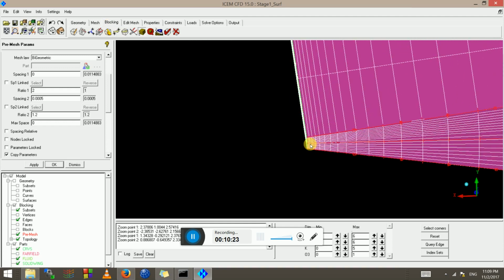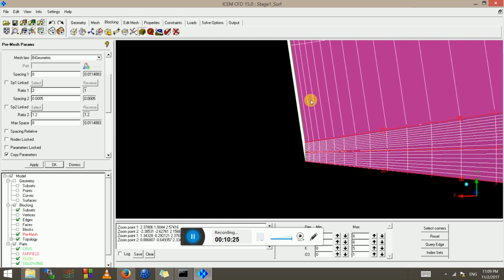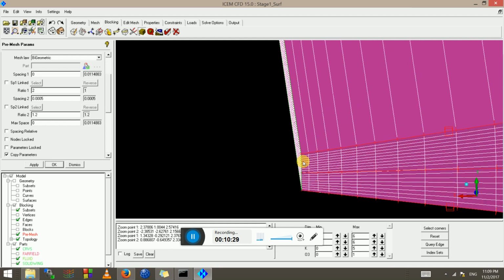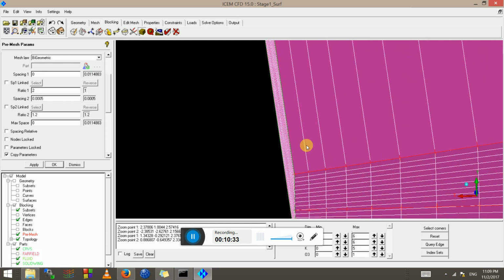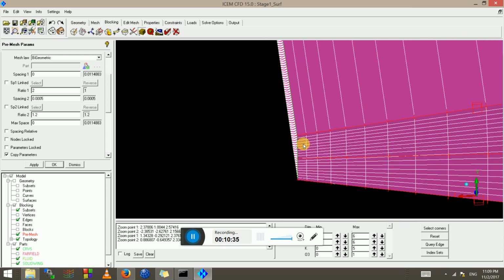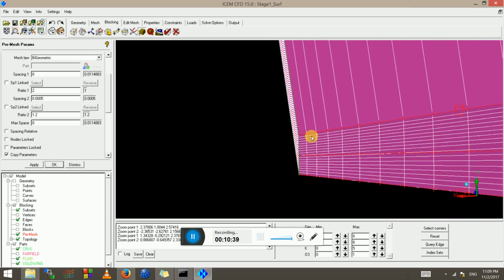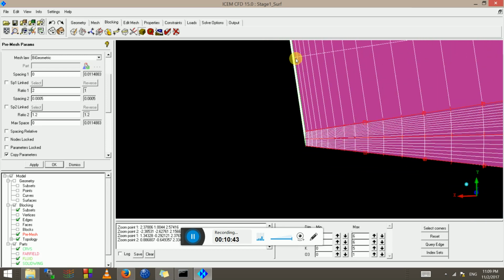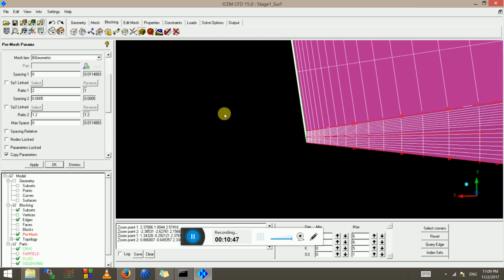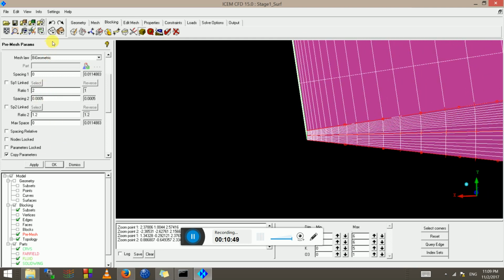But if we consider any flow that's going to flow span-wise due to some asymmetry or something, then we have, for any reason, to be honest, we have these cells quite small and these ones quite long in the z direction. We can fix that by playing with the spacings again.